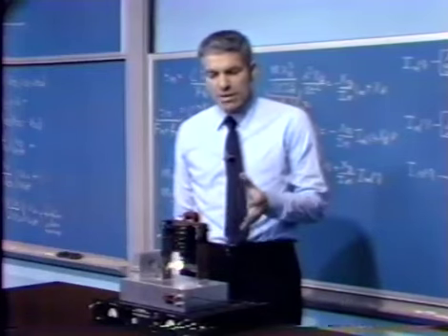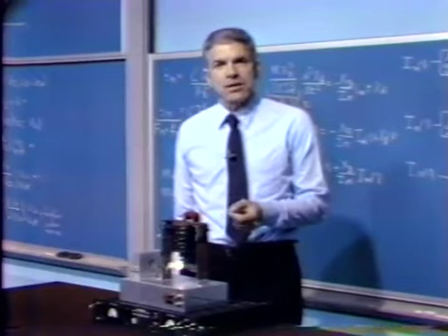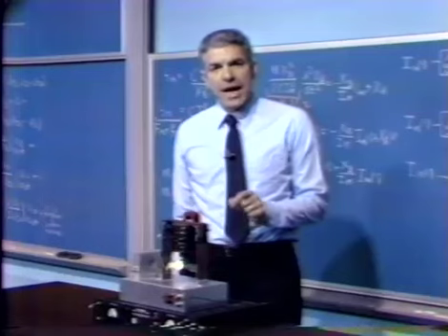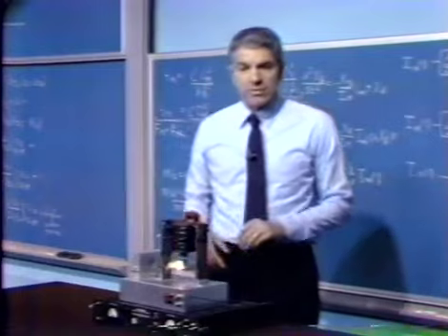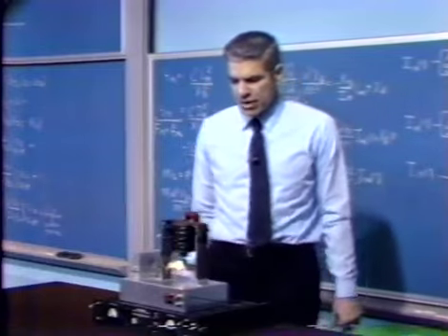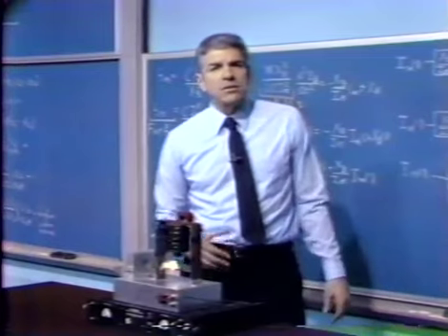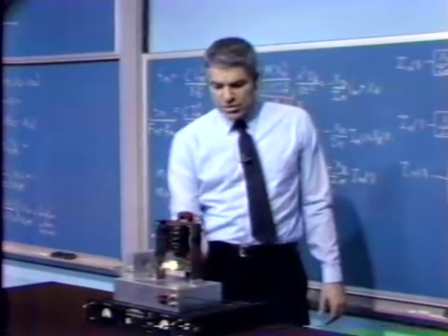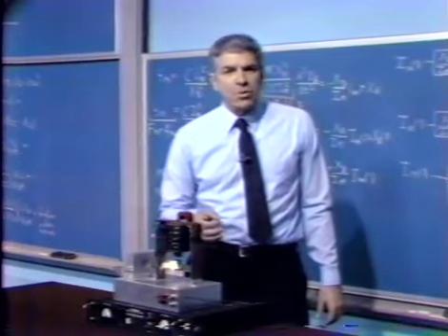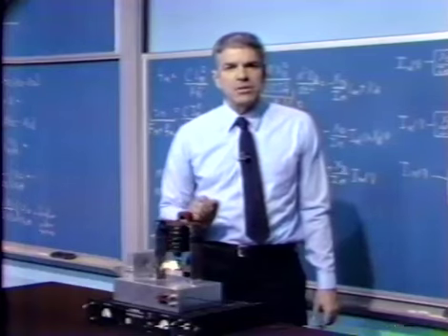Well, once we have that picture on an oscilloscope, we're very easily able to adjust the location of the zero and A naught to improve the nature of the transient response, and that becomes a very, very quick and easy adjustment to make. So once we'd used this sort of analysis to understand the system and to find which situation we were in, which direction should we go in terms of zero location and A naught to at least get the system stable in an absolute sense.